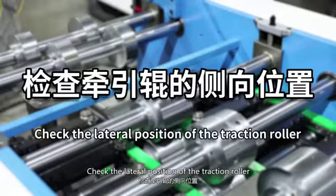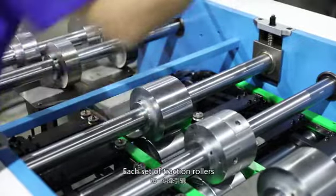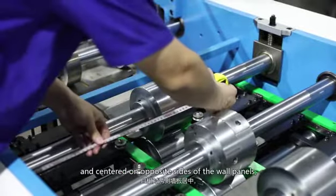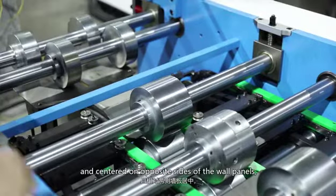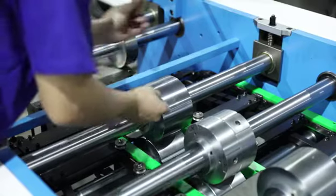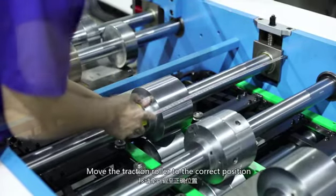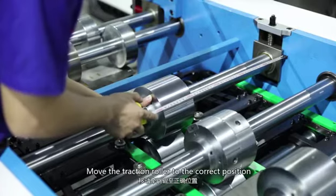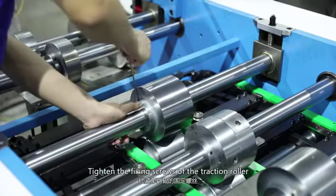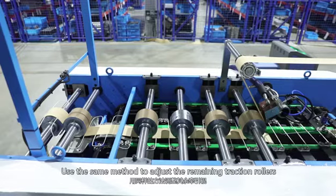Check the lateral position of the traction roller. Each set of traction rollers must be aligned and centered on opposite sides of the wall panels. If not, please adjust. Loosen the fixed top wire of the traction roller. Move the traction roller to the correct position. Tighten the fixing screws of the traction roller. Use the same method to adjust the remaining traction rollers.